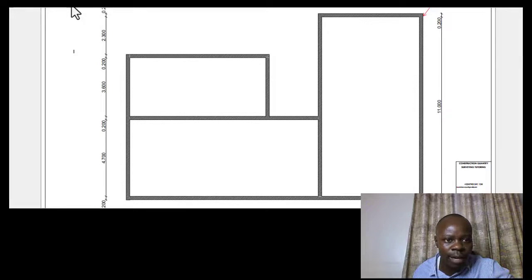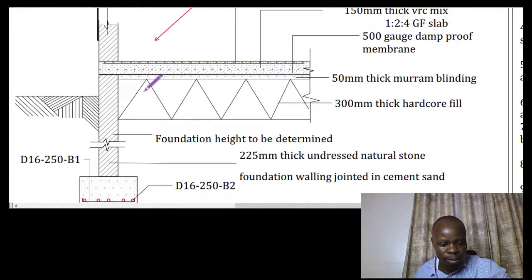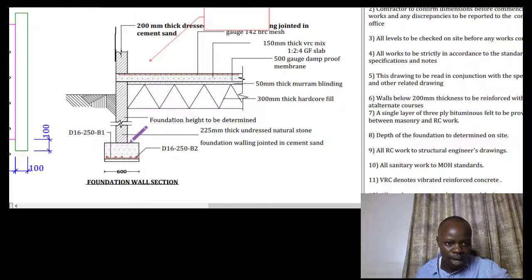So of course a reference is made to this strip footing. It's important that you understand that what we have in terms of the plan is up to the external face of this footing of the wall. But then at the clearance time, of course the rule tells us that we need to measure net, but at the clearance time you will be going up to the external spread.